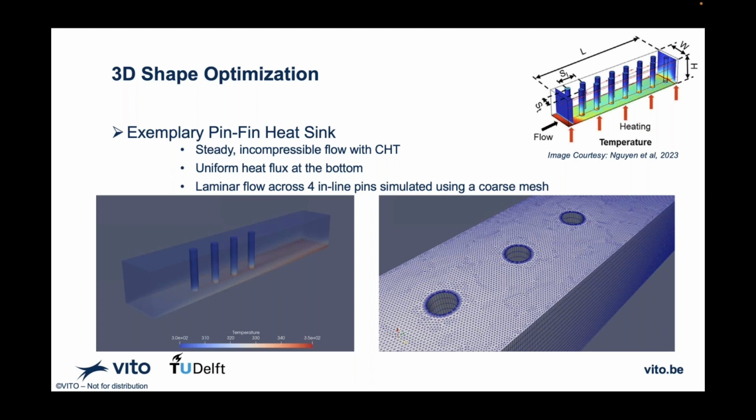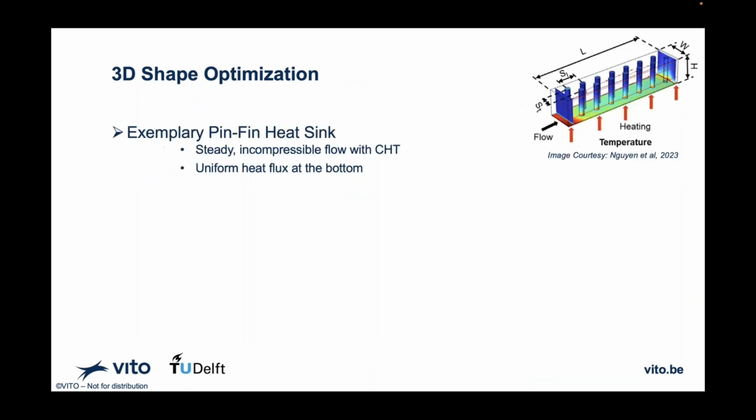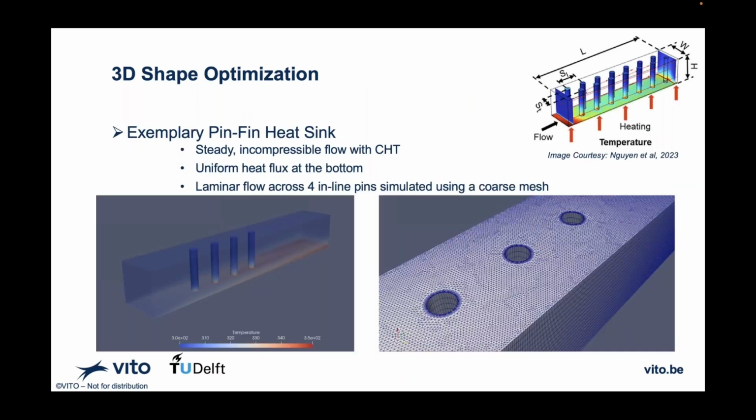So can you say a little more about alpha? How do you actually design the parameters? In this case, my alphas were the thickness variables along the camber line, in 2D as well as 3D. So we have the representation using a camber line and thickness distribution, and those thickness variables were allowed to vary, not just in one plane but also along the 3D profile as well.